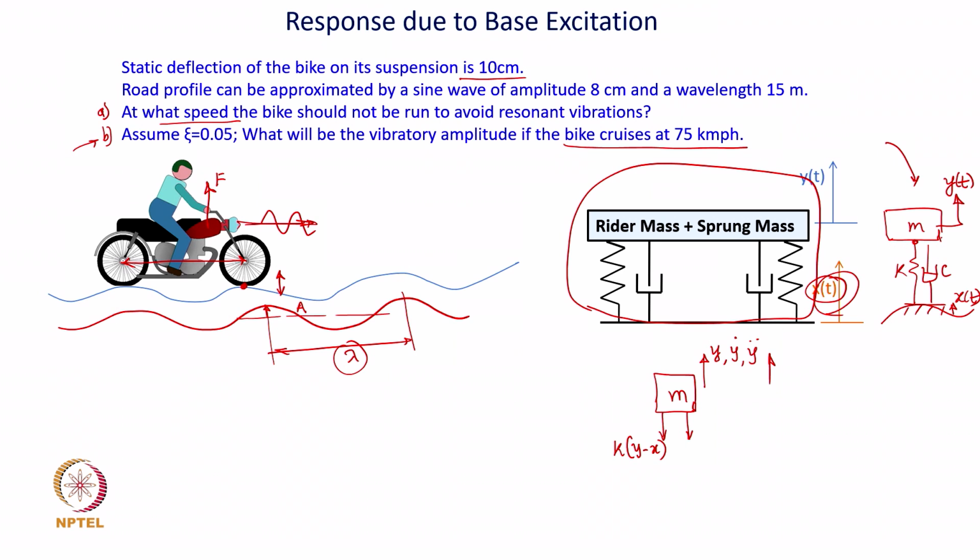We are ignoring, because we have discussed all that, once the mass is put on the spring and it deforms, your y of t is actually being defined with respect to the already deflected position, static deflected position, right. So, static deflection mg and all that will not come into picture here as well. Okay. Now, after this, what is the dissipating force? Similarly, there is no need for a further explanation here, that also will follow the same process. Now, you apply to get the governing equation once the free body diagram is made up. M, now will it be m y double dot minus x double dot here?